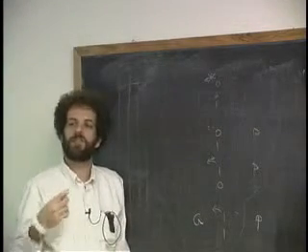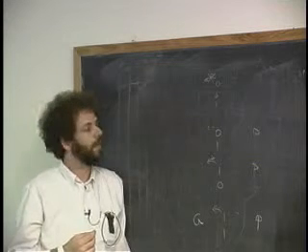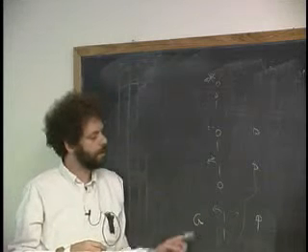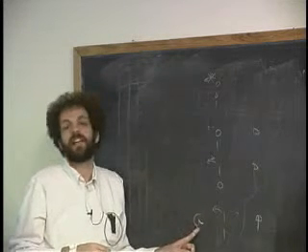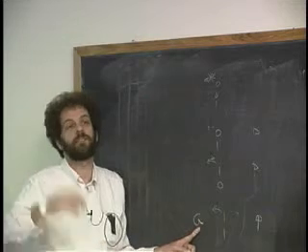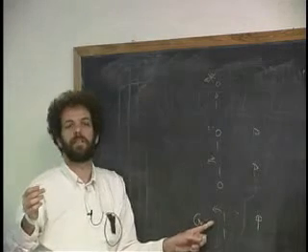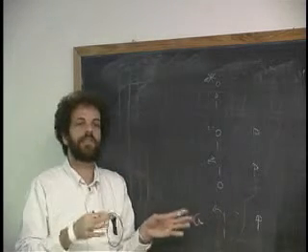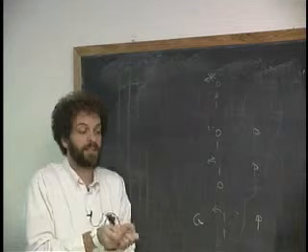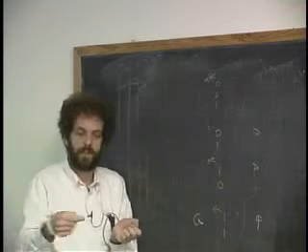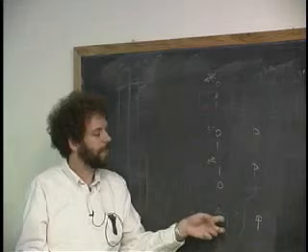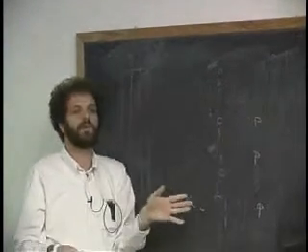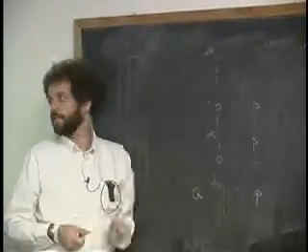Now this decision, do I generate or do I propagate, is a decision that can be made beforehand, before the carry comes in. First of all, the generate, you can even take action on before the carry comes in, because it doesn't matter what the carry in is, in this case, you just generate the carry. And in the propagate case, you can get all the work done and all set up, so you're just waiting for this last bit to come in, which is a slow bit that's going down the chain. If I have two 1s, or if I have a 1 and a 0, I get all set up waiting for the propagate to happen.